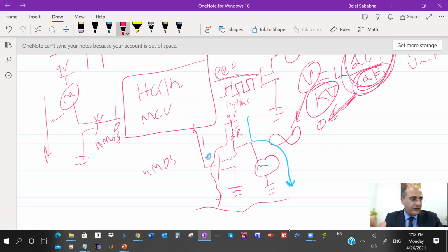What is better? Well, it depends on your application, right? If your motor is almost all the time on, and sometimes you need to turn it off, it saves you power and energy to write a 1 sometimes, and 0 all of the time, right? While the opposite is also true. If the motor is usually off, so you're usually writing a 0, and sometimes you need to turn it on, you write a 1. And this applies to any other actuator, of course. If it's a PWM, it will not matter, right? You're always switching on and off real quick.